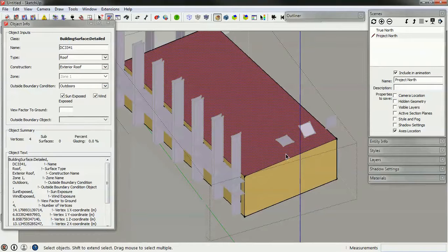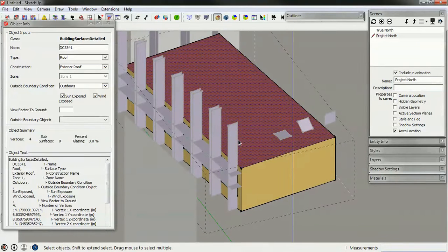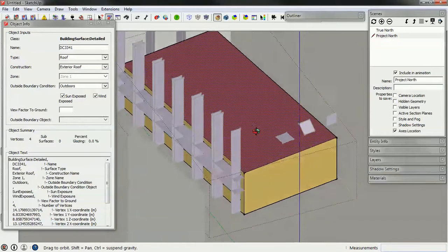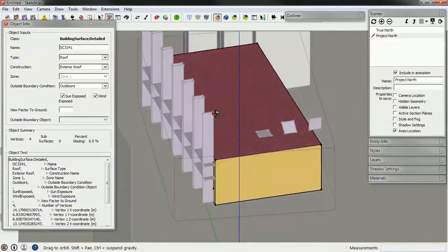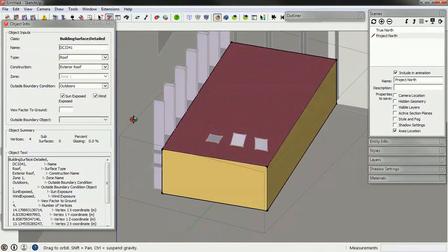And theoretically, there's no heat transfer occurring between the computer lab and the room upstairs. Now, in real life, there is, because the internal loads are different. But it's close enough, and I would encourage you all to use this type of logic, that it's essentially adiabatic. And what adiabatic means is that there's no heat transfer.